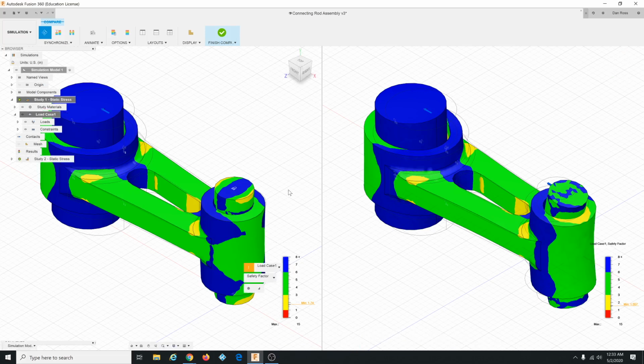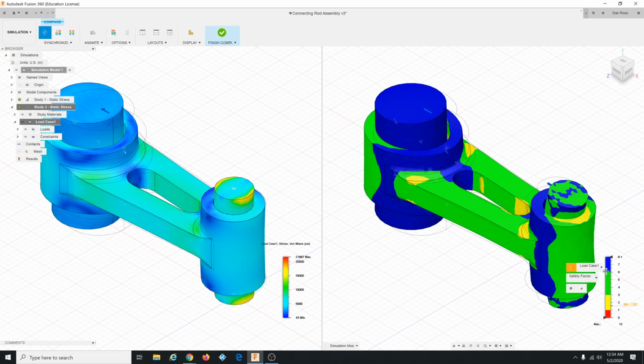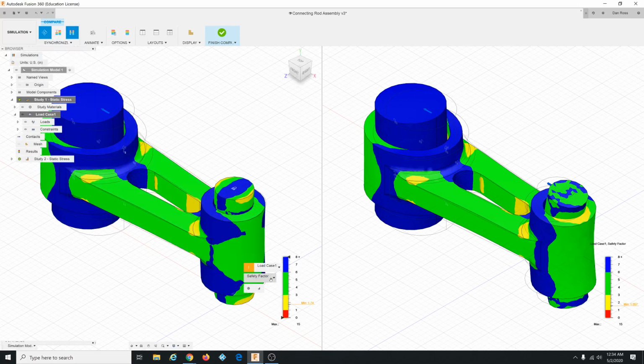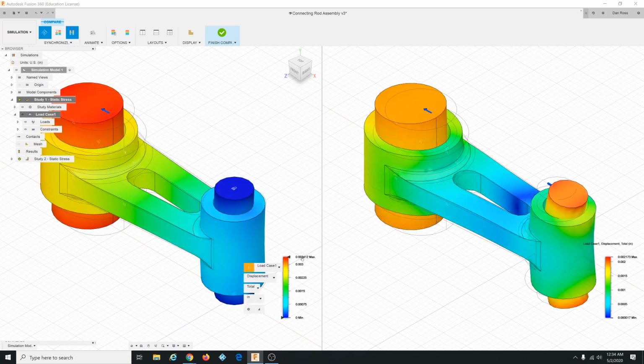Okay, then you can, let's see, safety factor on this one's 1.74, and on the other one it's 1.55, and the stress is 21,666, the max stress. On this one, it's no, they're not synchronized. Synchronized result type. Stress. It's 24,000 versus 21,000. Displacement is 0.0034 versus 0.0021.